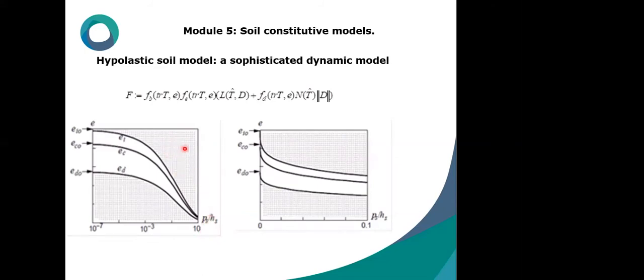And this gray part shows the impossible state for the soil grains. This model can properly simulate soil dynamic behavior and the hysteresis loop generated during seismic excitation. It also can show soil-structure interaction very well. You can see the tensorial equation of this model here, as I said before.